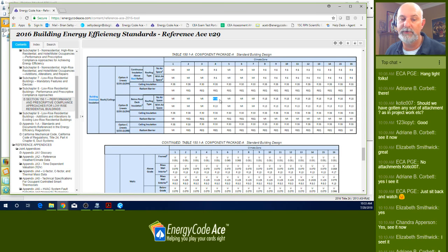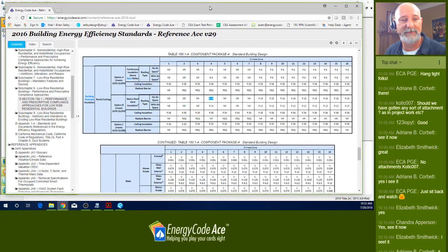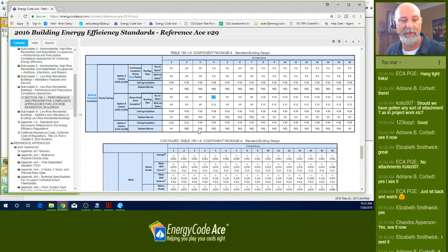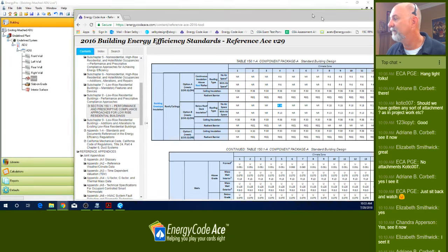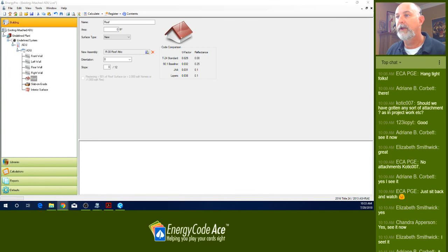Now we could choose another strategy for doing this, meaning that we could do option A, which is above roof deck insulation, or if we were doing a conventional HVAC system, we could configure that with the ducts in conditioned space. But in this case, the client information said they wanted to use a ductless mini split system, therefore we're not going to be able to use that option C. So okay, moving right along.